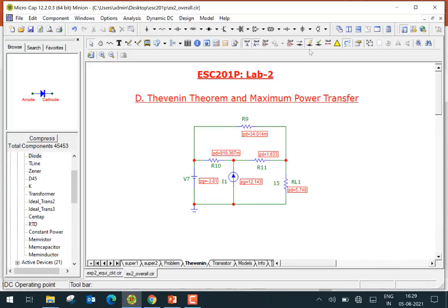Okay. Now you could do that by, for example, finding out what is the equivalent resistance of the rest of the circuit. So we could do a Thevenin's transformation of the rest of the circuit and find out, for example, what is the Thevenin's resistance. And then you know the theorem of maximum power transfer, that whatever is the Thevenin's resistance, you should choose the load resistance to be equal to that Thevenin's resistance, right? So that's where Thevenin's resistance comes into the picture here.